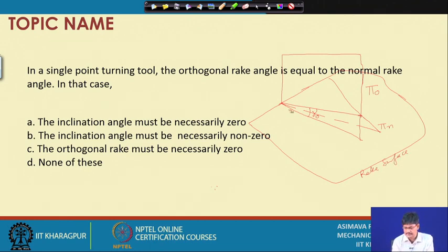On the rake surface, the orthogonal plane has come straight vertical, while the normal plane is slightly inclined. Now, if you look at the plan view, the rake surface has the cutting edge this way, so that if I go on reproducing the cutting plane on the rake surface, they will all come to be parallel, and the cutting edge here makes right angles with the normal plane.